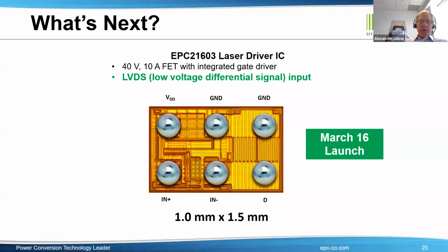A couple of things there: these dual edge control schemes, where you turn it on and turn it off, all the IToF ones are dual edge control. But for the very long range DToF ones, dual edge control has the danger of eye safety. What happens if you can't turn it off? And so some people struggle a little bit with that. But in general, as John said, it is hard to make a longer pulse than a short pulse. And if you make a longer pulse, you cut it off by turning on the FET or by dissipating it through the FET.